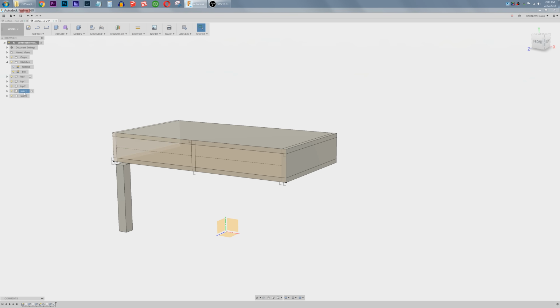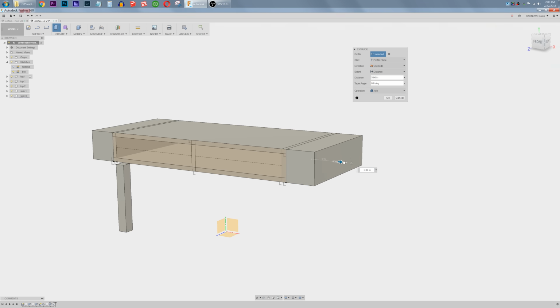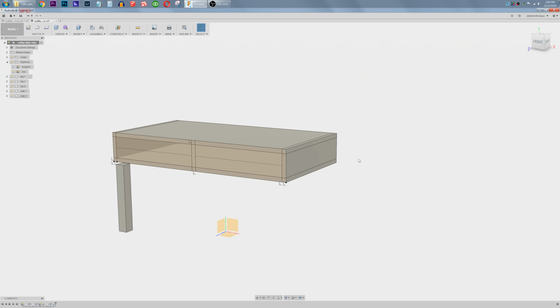Now, you see it says side 1, side 3. That's because that's the third instance of this copy. I just deleted the second one. I don't know why I added that. It was an accident. But what this does is if I go to E for extrude, this outside face, you see if I modify the outside over there gets modified. So that's the position that I want it to be in. I'll press escape to back out of that.